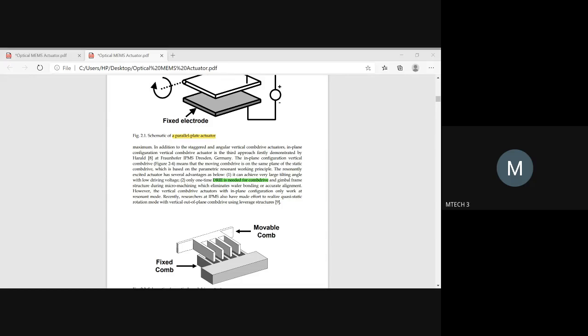Sometimes we etch out only 25% of a substrate. But if you need an etching process to get the required pattern at deep depth, then you have to go for the DRIE process only, which is nothing but deep reactive ion etching. It mainly depends upon your requirement. In some cases we etch in the substrate, and in some cases we etch above the substrate. It depends upon whether you're doing bulk micromachining or surface micromachining.